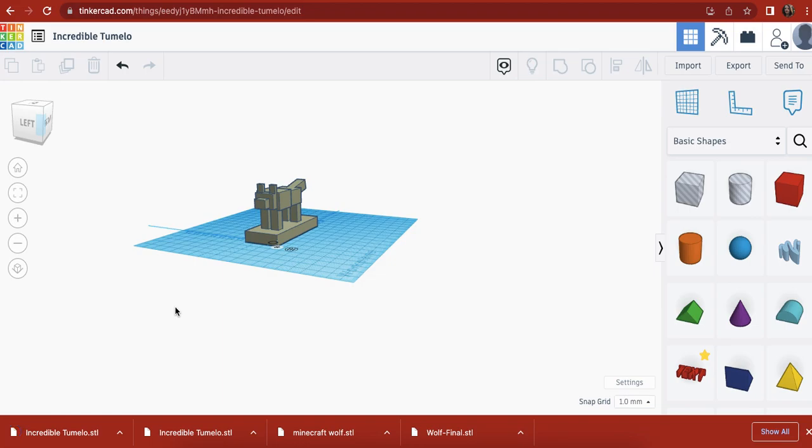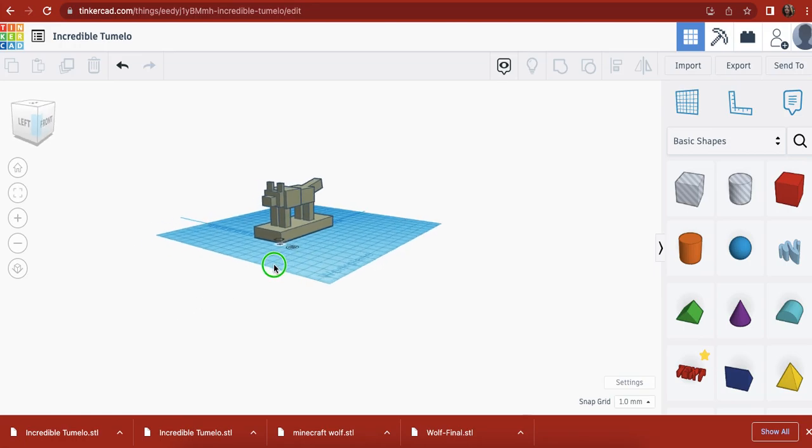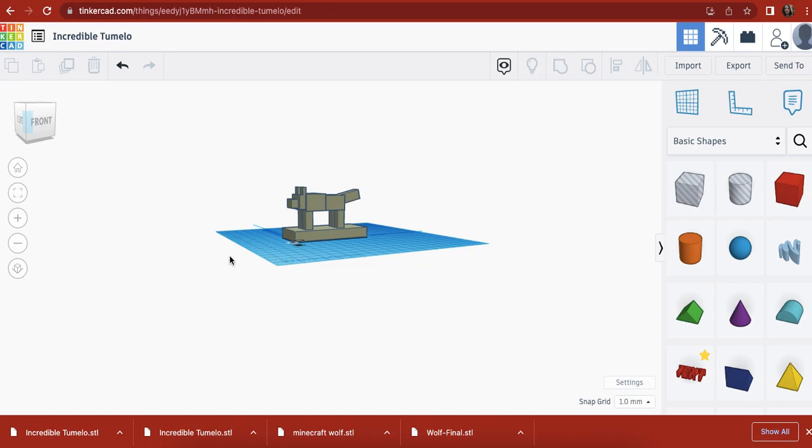Now, I am going to download something called slicer software in order to prep it for 3D printing. Because while we now have our 3D model, we need to go through the steps of anticipating all the needs of the printer, putting the settings in to create our STL into something that's referred to as a G-code. That finalizes the formatting created for an object in order to prepare it for printing.